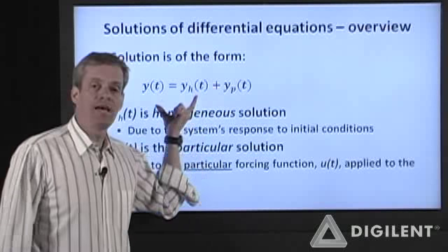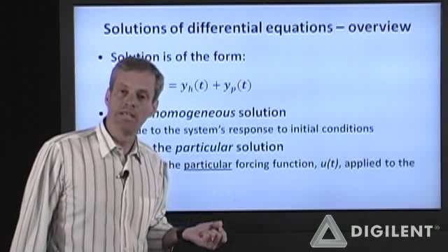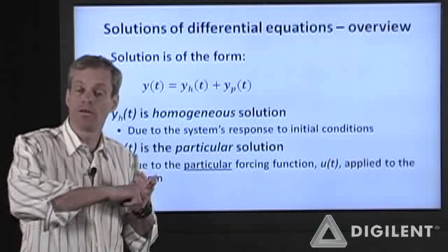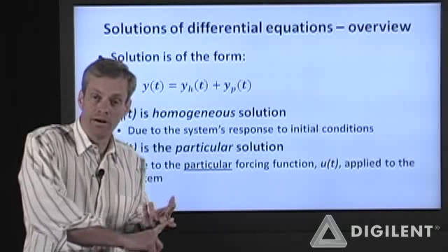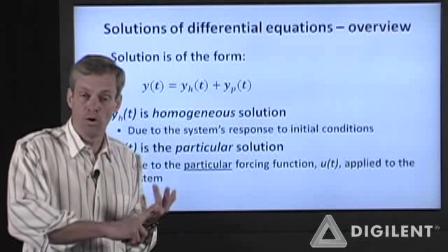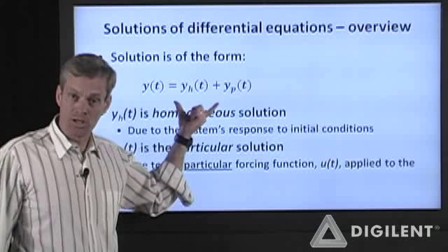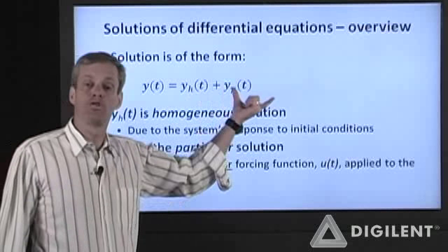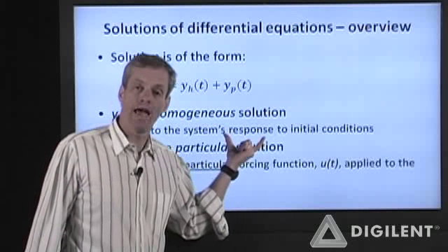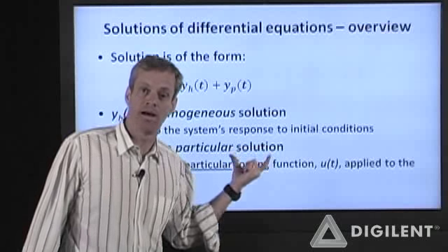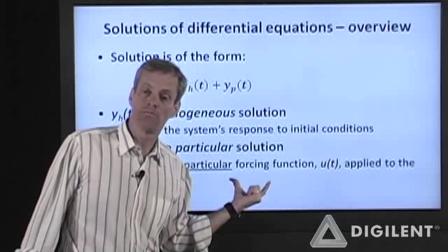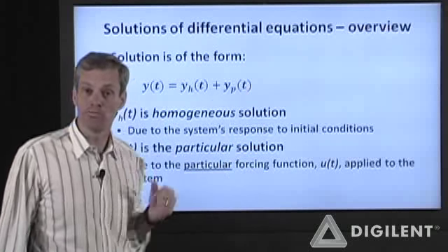We can sum these up because this is only for linear systems. Remember, I said we were talking only about linear, ordinary differential equations with constant coefficients in this class. Since these differential equations are going to be linear for us, this superposition works. We can look at the system state response and the system input response separately and then superimpose them.